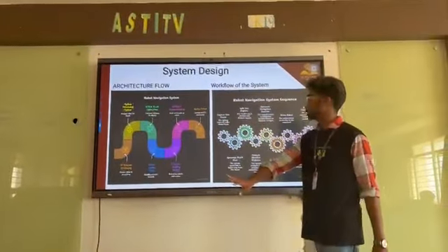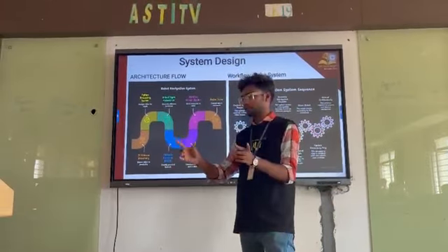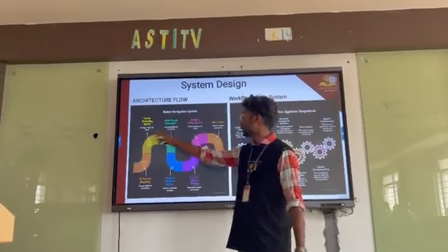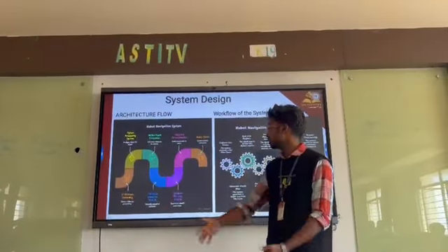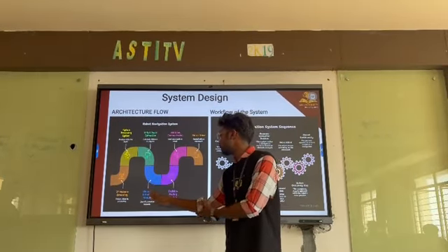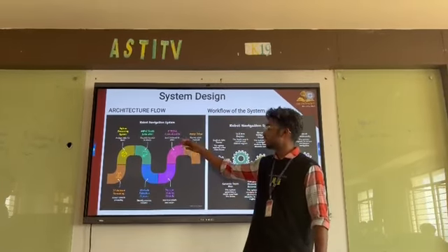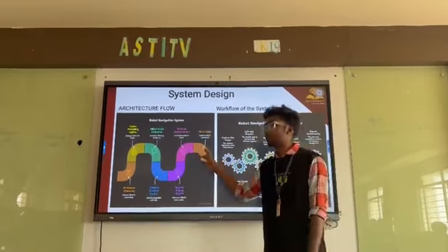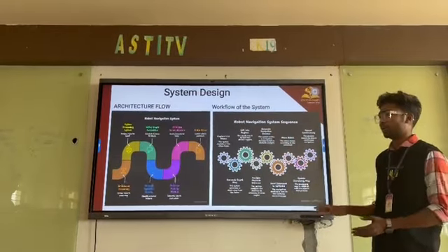So as I showed in the model, the IP webcam streams the photo frames. The Python and the MiDaS model, which is stored in my laptop, will be doing the ML work, and the obstacle detection will be done in the deep learning model itself. So the decision-making output will be coming in my laptop. That output will be sent to the ESP through Wi-Fi, and that makes the decision whether to turn right or turn left. So this is how the robot navigation is working.